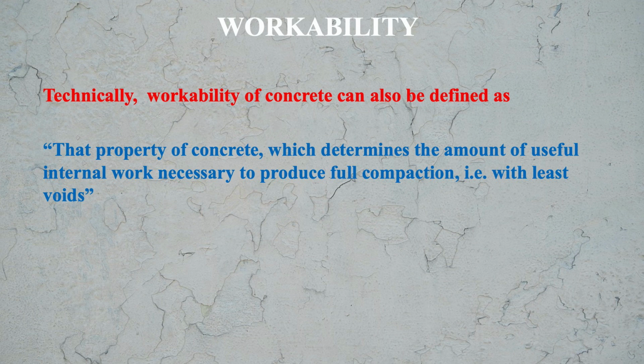Now another definition: technically, you can define the workability of concrete as that property of concrete which determines the amount of useful internal work necessary to produce full compaction, that is, with least voids. Full compaction means the amount of voids left is minimum.